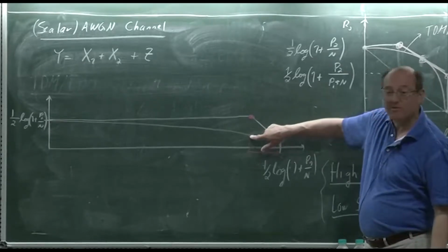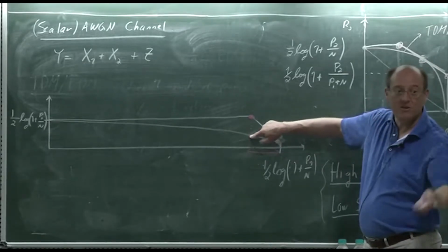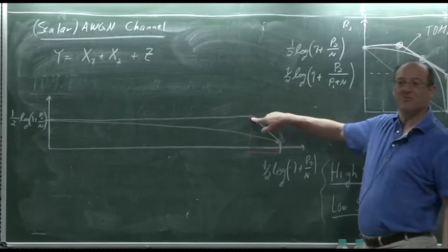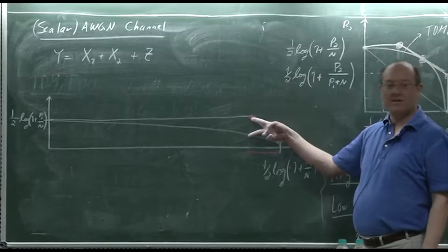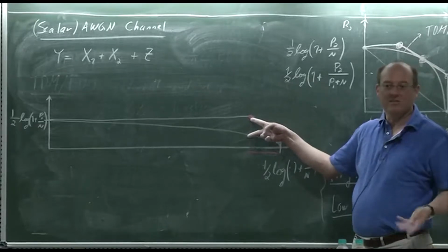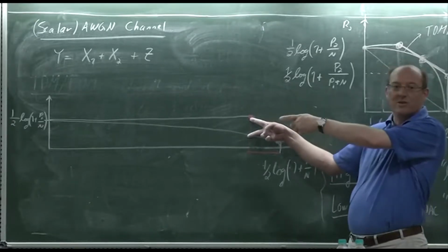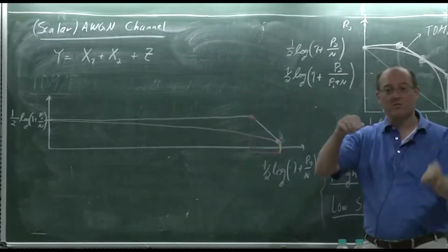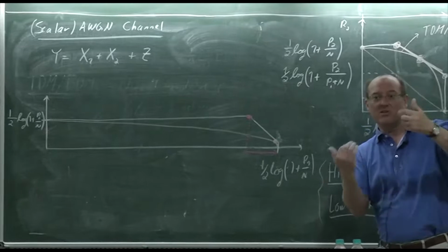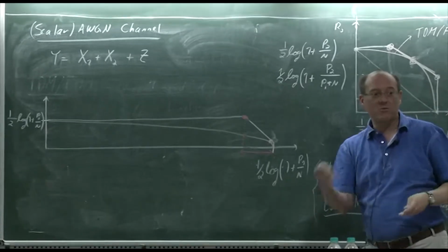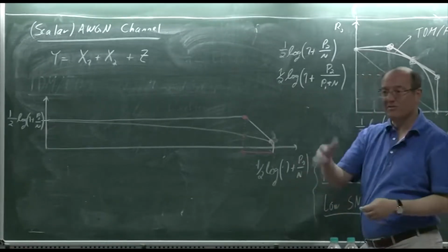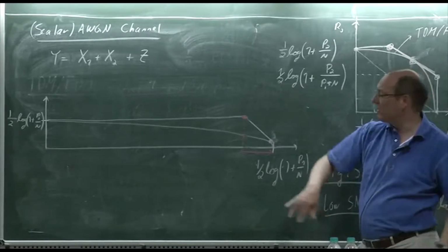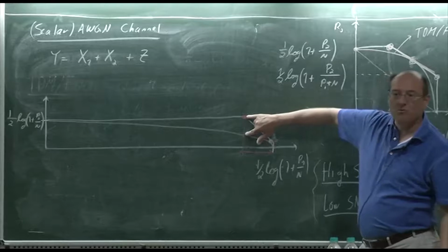But now, doing successive interference cancellation, rather than 100 kilobits per second, we can offer them 200 kilobits per second. So that's the business case for using successive interference cancellation. We have to do a lot harder work: decoding, subtracting, synchronization, resampling. It all takes processing power, right? It's not so easy to do, but a base station could probably do that, and that's what you'd have to do. That way you improve the rates, okay?